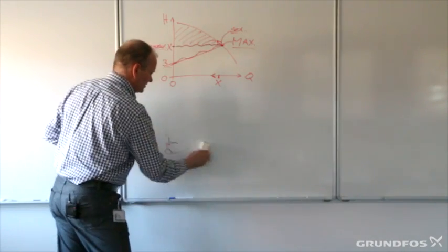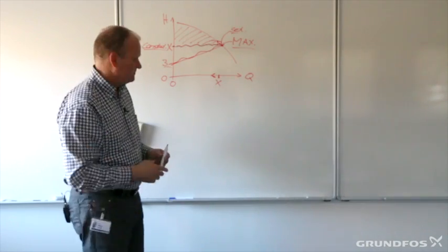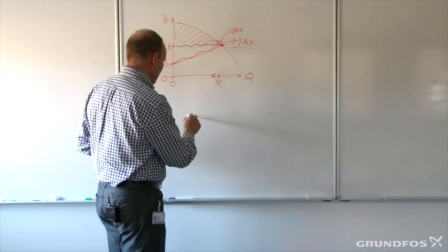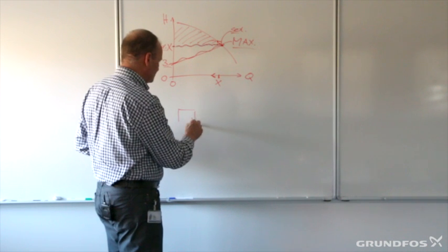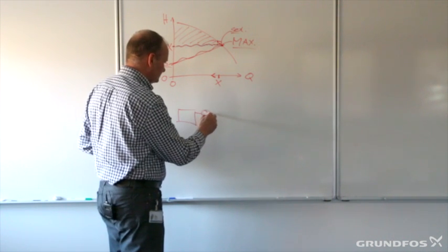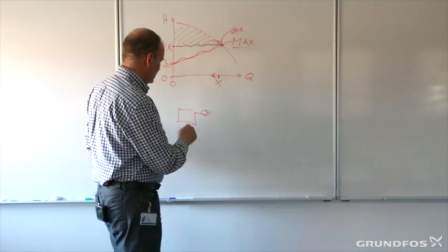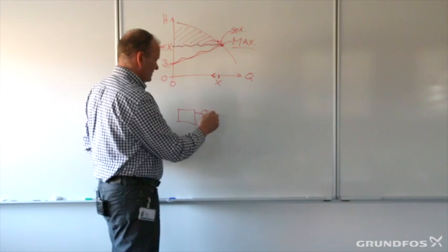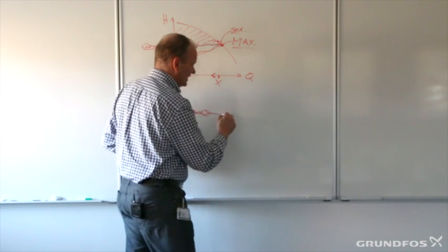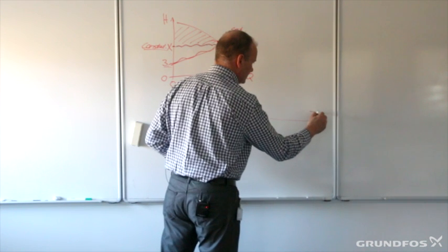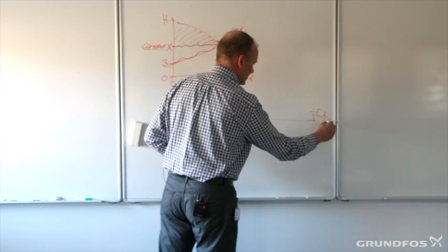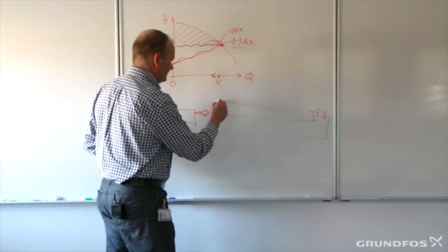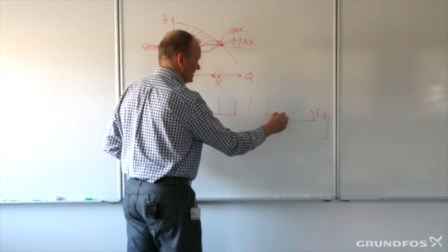So proportional pressure, where should we use that? That's more like if we have a very widespread system where there's a long distance from the heat source or cooling source and out to the final consumer, where you have different consumers on the way out here.